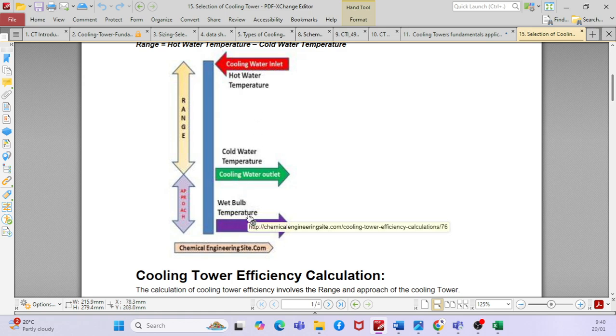But let me ask you something here. When we are trying to find the GPM for a condenser, we say tons into 30 divided by delta T, correct? Yes, the tons is the tons that you get from your selection. Then the delta T would actually be your range essentially. Range. Clear, right? Yeah, got it.